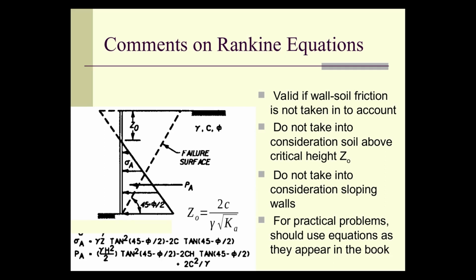Principal among those would be sheet pile walls made out of very smooth material, such as vinyl and pultruded fiberglass, and to a lesser extent aluminum. I would not use anything but Rankine on walls like that. They're just not there, and there are other reasons for that as well, but that's the principle.